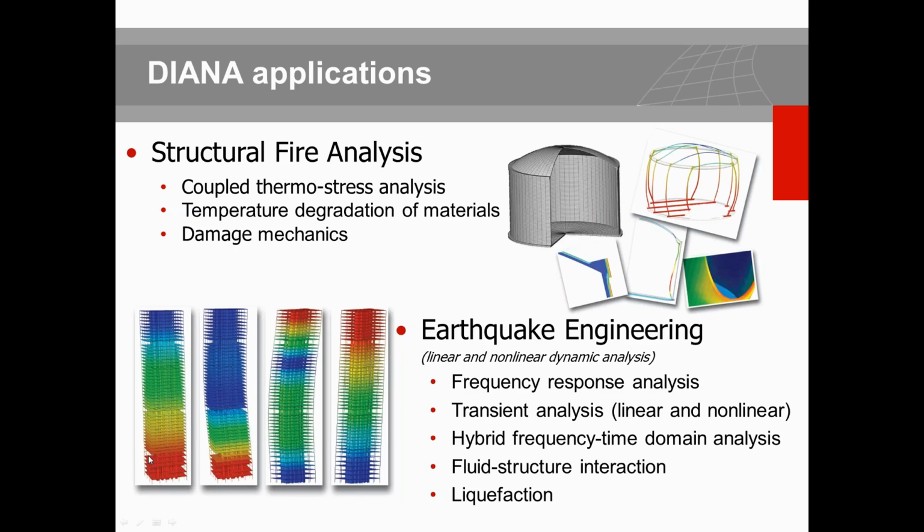Fluid structure interaction enables you to exactly compute the hydrodynamic pressure on the structure, and liquefaction analysis is based on the liquefiable material models that we can assign to the sand and soil material model. So we have that based on different constitutive models.